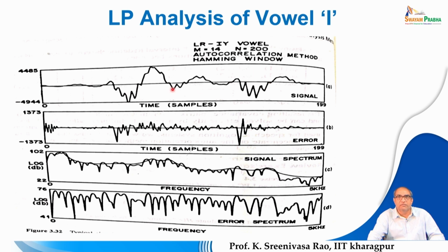How do you get that? If you apply a Fourier transform and then take the absolute value of the signal, that gives you the magnitude, and then take a log of that, then you can observe this rippled waveform. At a very gross level, the rippled waveform has very high energy over here, then a slight peak over here, and another peak over here and here, and so on. And this is the normal spectrum computed by using FFT analysis.